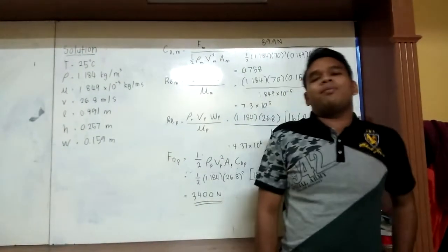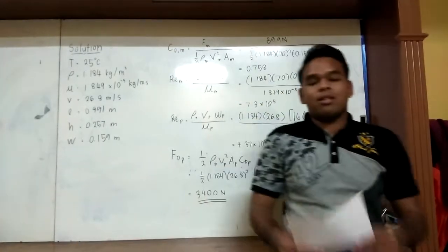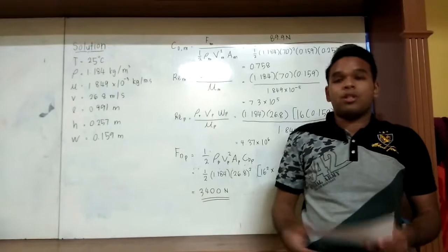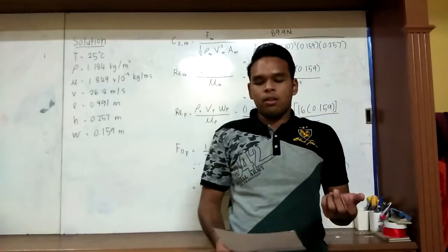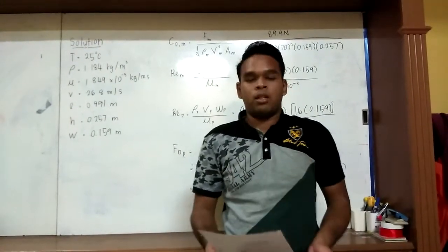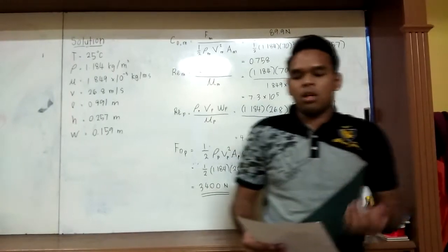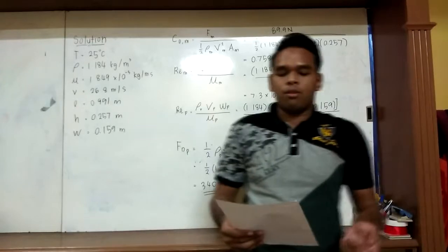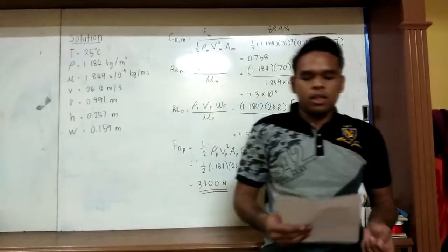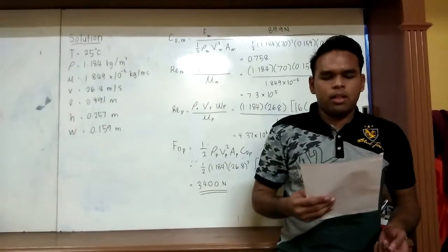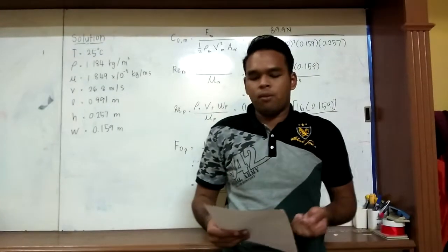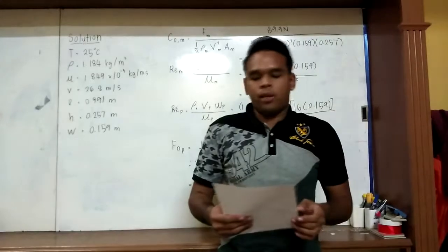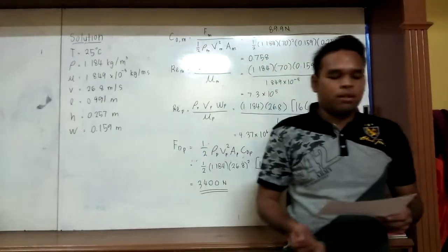Okay, today I would like to present a topic about dimensional analysis. Firstly, I will introduce what dimensional analysis is. Dimensional analysis is to generate non-dimensional parameters that help in the design of experiments and in the reporting of experimental results. Second is to obtain the scaling laws so that prototype performance can be predicted from model performance. And lastly, to predict trends in the relationship between parameters.